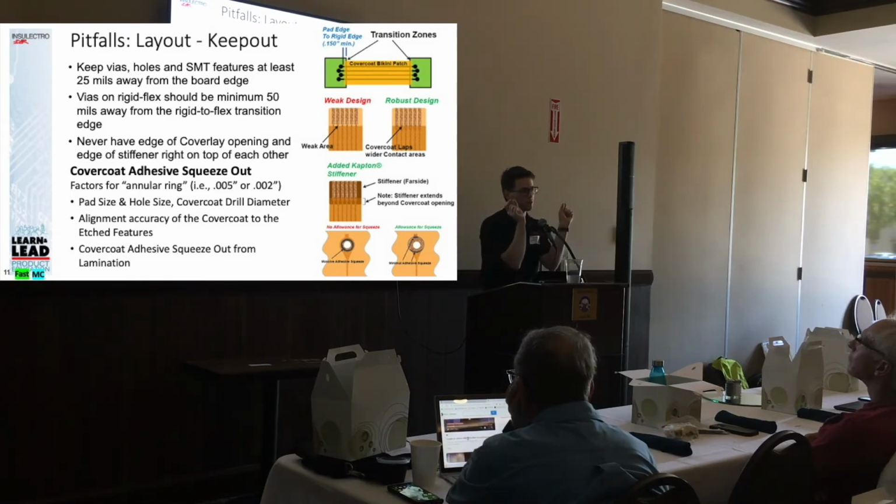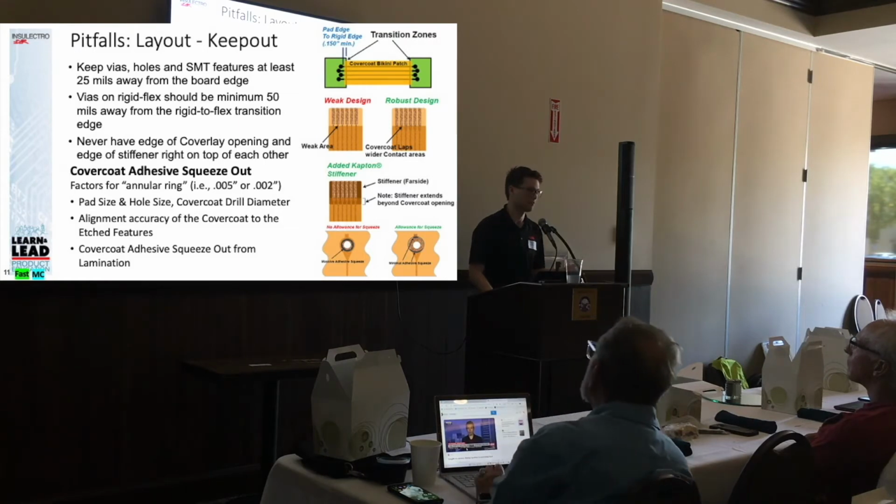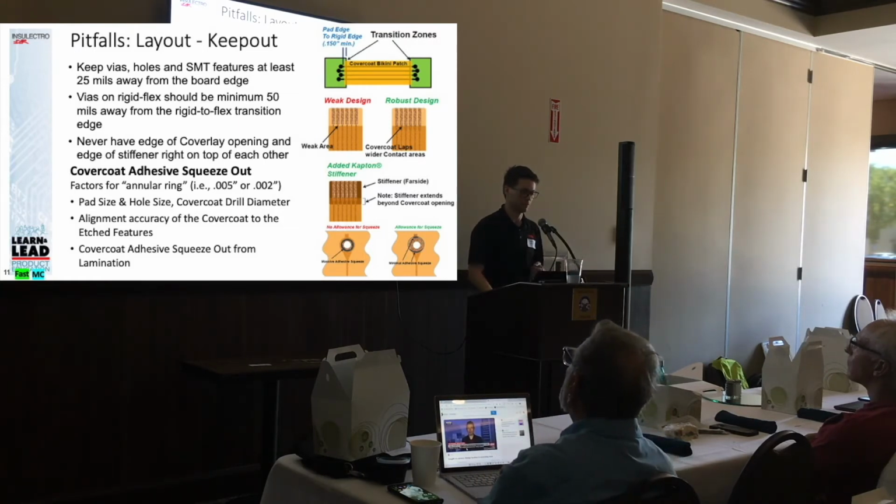And we want to make sure we keep the drilled PTHs and other electromechanical structures away because, again, those acrylic adhesives expand and can put undue stress onto our structures and cause early failures. This is one of the largest design flaws that I see with individuals starting to lay out rigid flex or flex designs their first time. It's something that you want to avoid.